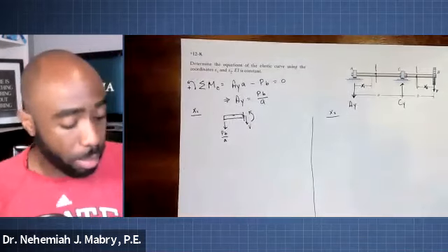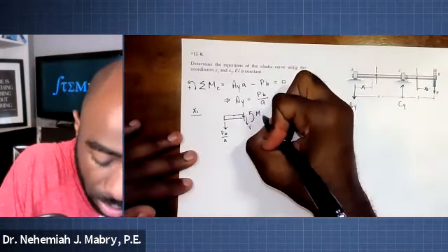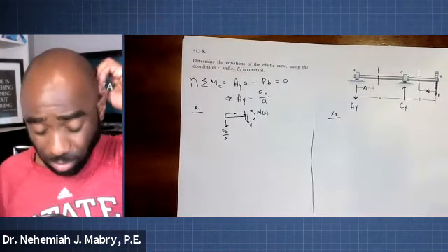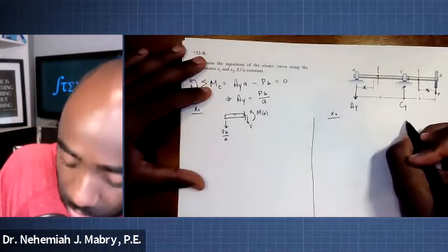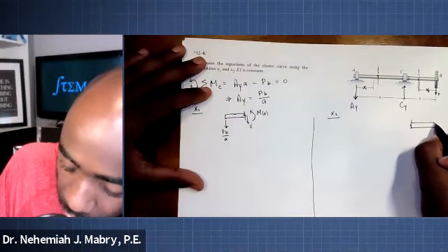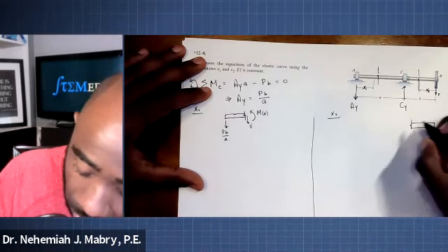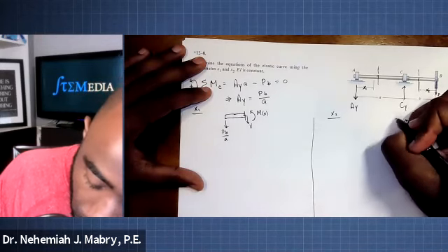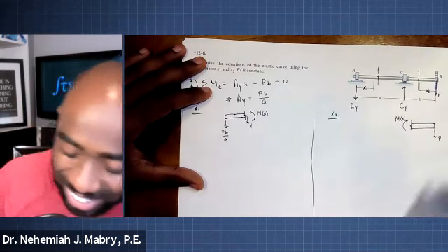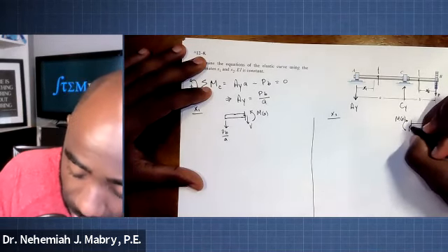We're going to get the moment equation, and this is going to be determined by MX. Over here, drawing the cut from this side, we know we've got P going down here. We're going to draw a moment here, and there's obviously a shear force going up here.